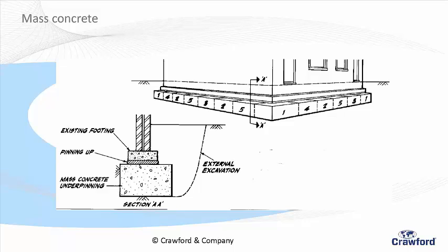Imagine if you had to go deeper than, say, a metre and a half or 2 metres. If I had to go down to here, I wouldn't be digging like this, would I? My excavation would start from the back here to get down there, wouldn't it? So I'm moving all of this material, and imagine digging through that sort of crack. Disaster. A lot of material, and I've got to get rid of it somewhere as well. So it's a mess, it's very expensive, and it's dangerous. So as you go to depth, you need to come up with other solutions.